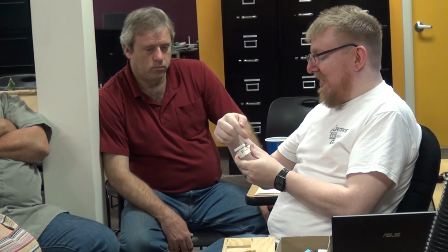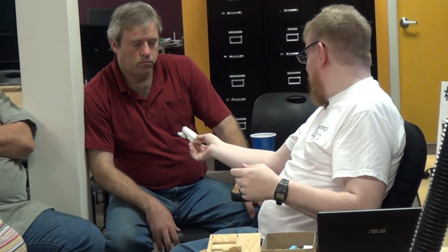Part of that's because your bit is not necessarily within a thousandth of an inch. It may not be exactly 1/8, and the material moves out of the way. There's a certain point where you machine enough away that as you're cutting it, it just pushes it out of the way versus cutting it. So when I redesigned it, I cut this out at an exaggerated size, moving the bit over a little so that it's cutting a bigger pocket, and then it cuts on the inner part that's smaller. It takes away that problem altogether. So this machines out the edges, it cuts the holes, it does everything.